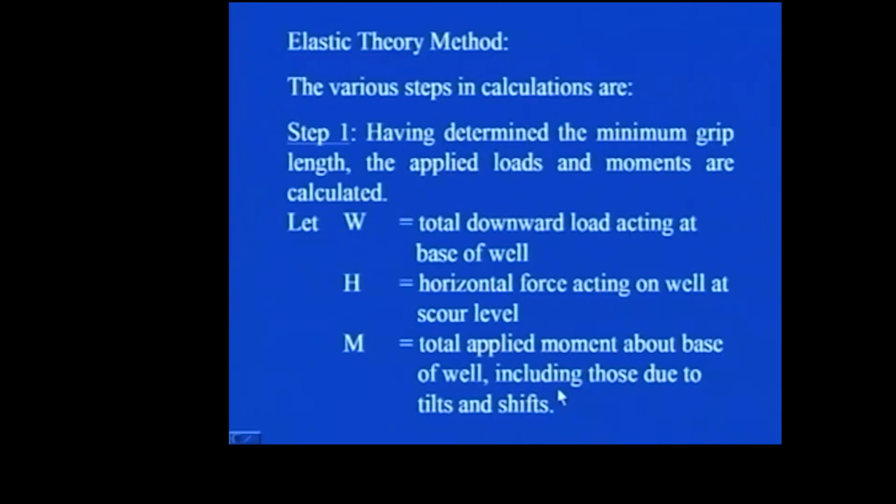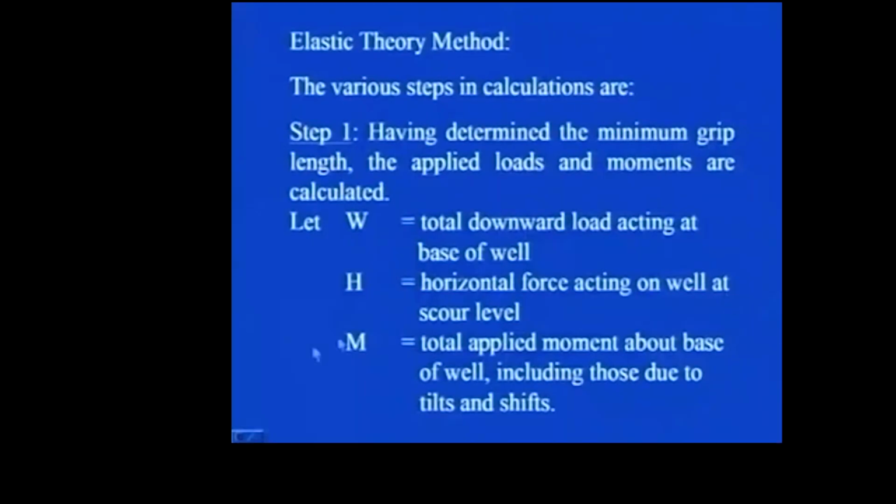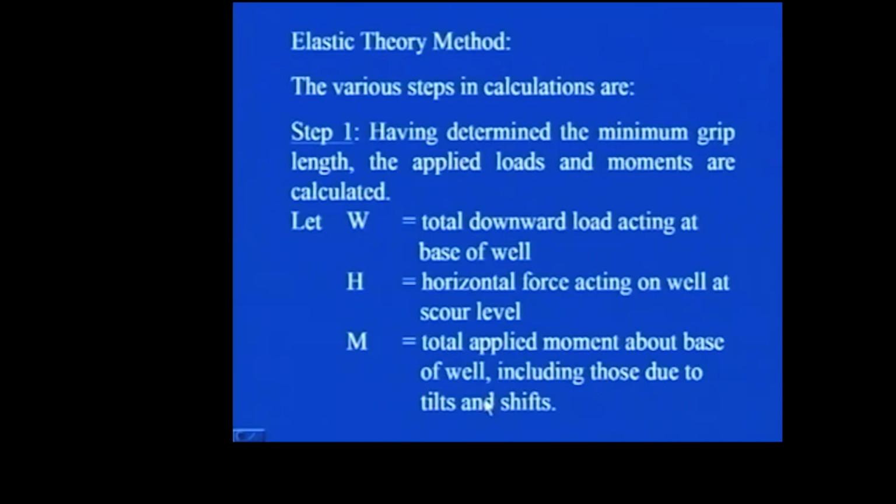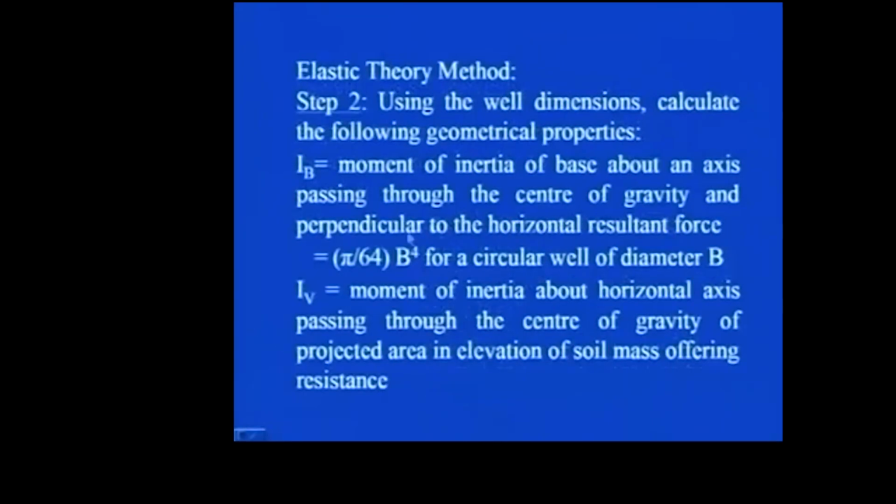Because in the last class I was telling you that these tilts and shifts should not be present, or even if they are present, they should be within permissible limit, because they cause additional moments which, if you do not take care of them during your analysis procedure, can be hazardous to the safety of that well foundation. Therefore, these tilts and shifts should be within permissible limits.